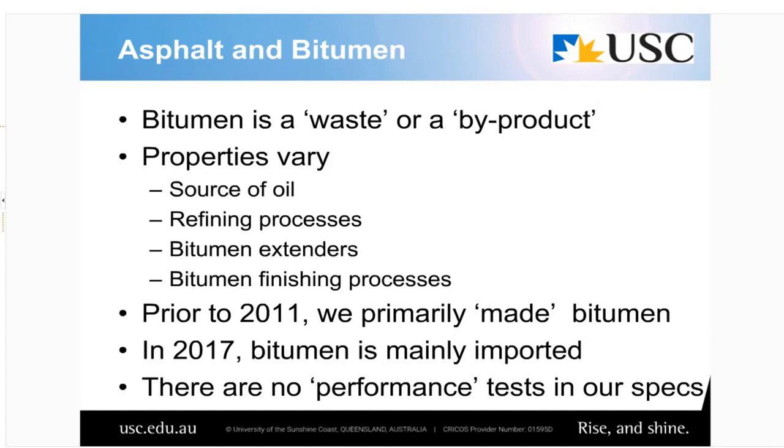The 1% lime is traditionally intended to reduce the risk of that occurring. The polymer modified binders certainly appear to help reduce that risk as well. There are other products called liquid anti-stripping agents that can be used in lieu of hydrated lime to essentially achieve that same moisture resistance, but in a different way.